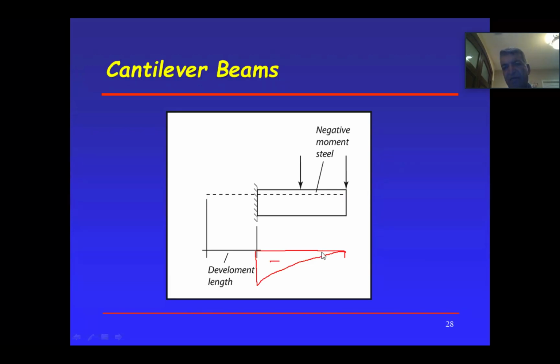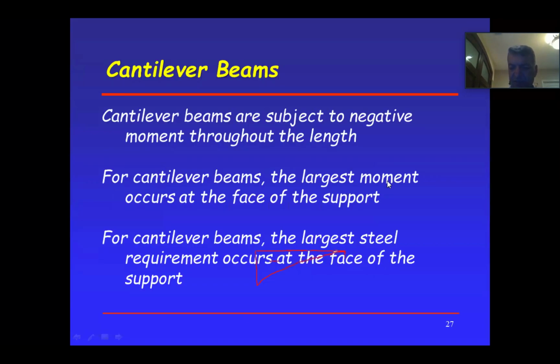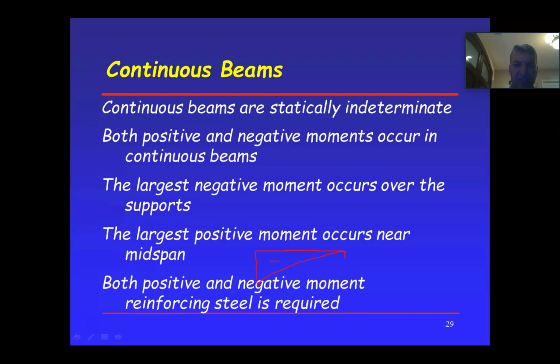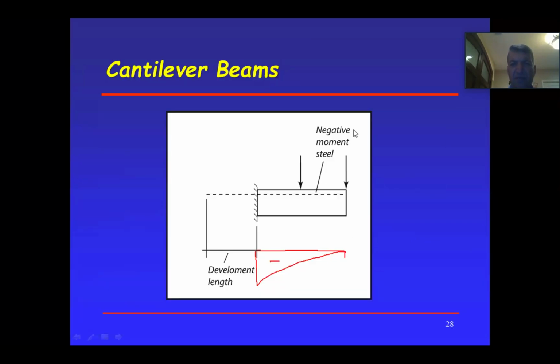But what we do in real life, we don't do that. We just carry the steel all the way. If it's a major job, in theory, you can cut your bars here and use a smaller bar to continue, and you overlap that. And that overlap, again, how much do I overlap? 50 db, 50 times the diameter. And if you have two different size diameters, use the larger diameter, 50 times the larger diameter. Okay? So that's what this is saying. So let me erase the moment here. Any questions?